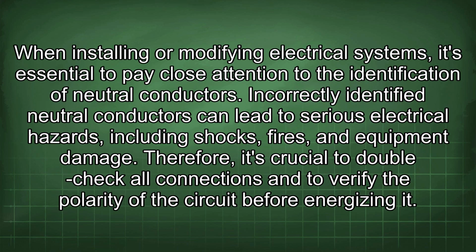When installing or modifying electrical systems, it's essential to pay close attention to the identification of neutral conductors. Incorrectly identified neutral conductors can lead to serious electrical hazards, including shocks, fires, and equipment damage. Therefore, it's crucial to double-check all connections and to verify the polarity of the circuit before energizing it.